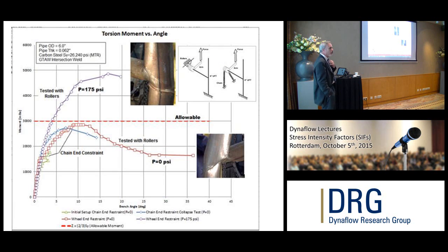This is the interesting thing. You'll see a whole bunch of new things with the nonlinear calculations coming in the next 6 months from us, I think, and potentially from other people. When you run a pressure calculation in ANSYS or our software or whatever, and you're doing an elastic analysis, if you take pressure right to the limit, you can't add any external loads to it, right? That's the problem. You've designed it optimally to pressure, so it doesn't carry any extra loads in the nozzle, because with a little bit of extra stress, the allowables are the same, so you're overstressed.